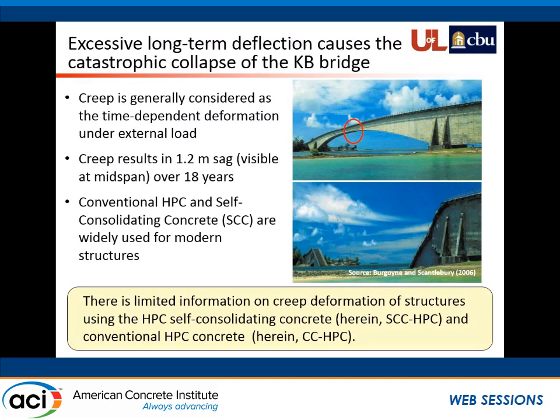It was built in 1978, and after about 16 or 17 years, the midspan deflection was about 1.2 meters. It's quite visible. People repaired the midspan and compensated for the deflection, but the deflection was not fixed and kept getting worse. Finally, excessive prestress loss and bridge failure occurred in 1996.